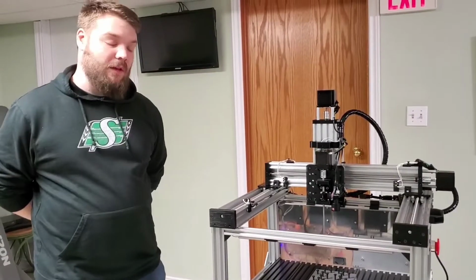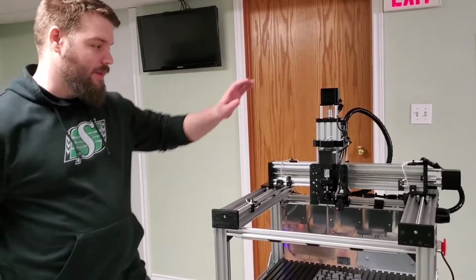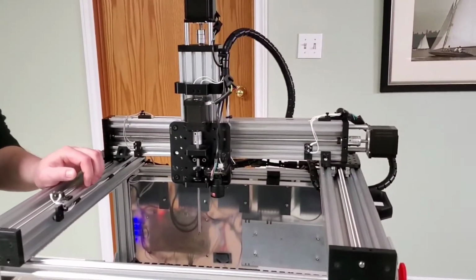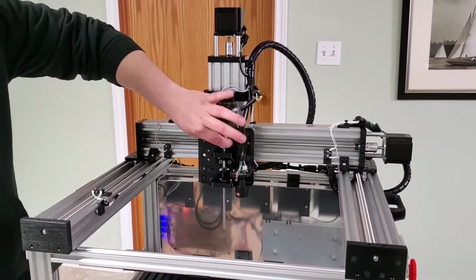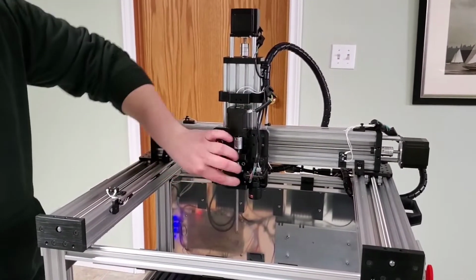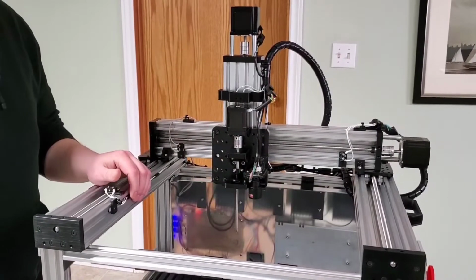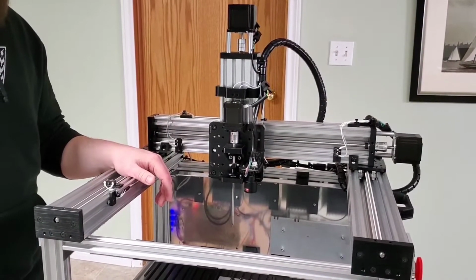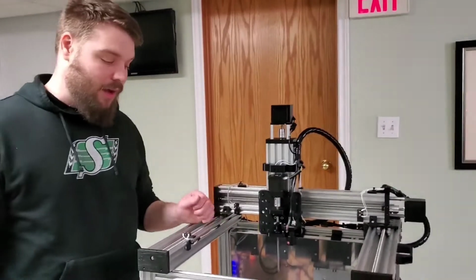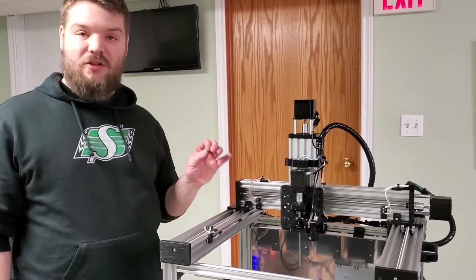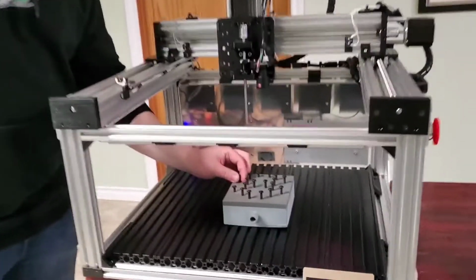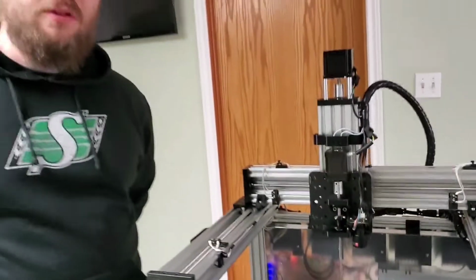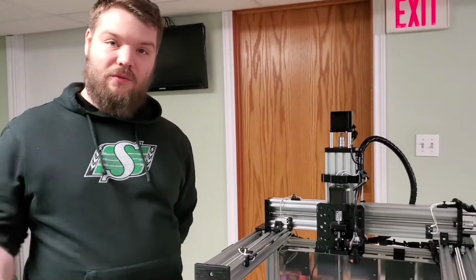Another part of the motor control subsystem that's quite important is the Phi axis. The Phi axis is being run off of this NEMA 17 motor that is connected by this flexible coupling, and also attached to the screwdriver shank is our homing encoder. This rotational encoder is going to help it home to its correct position, which is going to be at a 90-degree angle. Part of the pre-tuning process is that each screw is set to 90 degrees, and after each screw is turned, the system itself is going to keep track of its rotation.